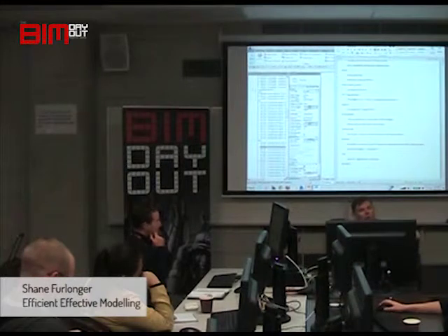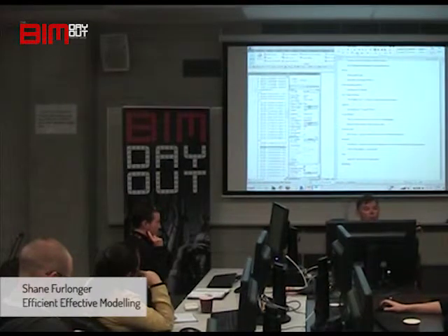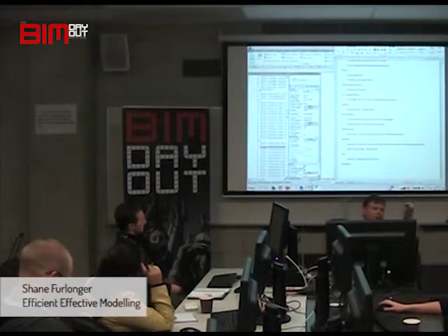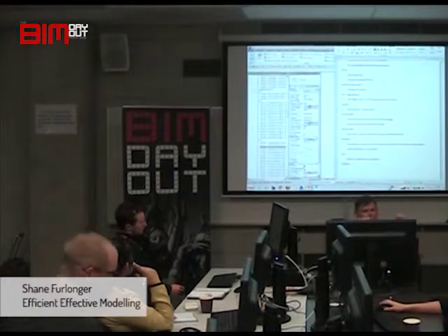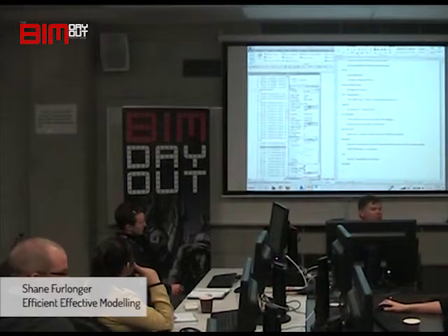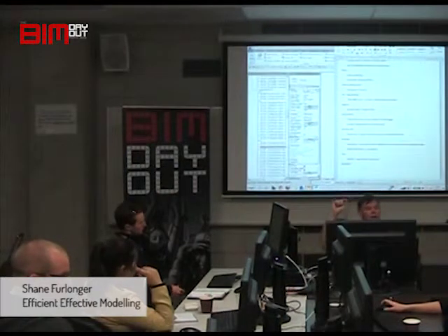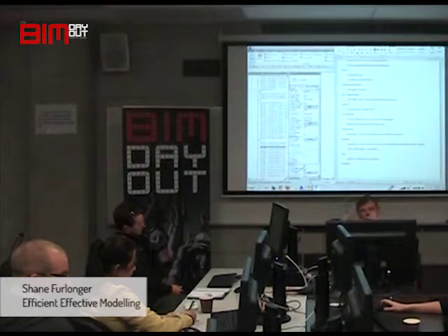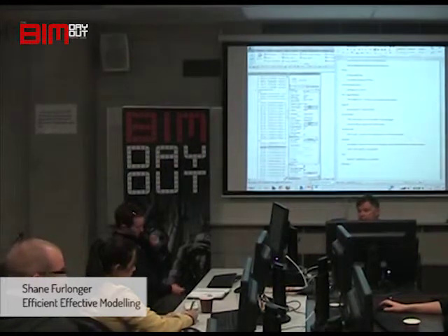You click on the wall, first time that wall's selected, it will ask you what the keynote is for that particular wall, if it's by element, and it'll call up your table, and then you go, okay, it's masonry, and it's this. This table then drops down into various stages and gives you an element that you can attach to the wall. It can either give you a code, depending on the tag type that you use, or the full description of what the wall is.